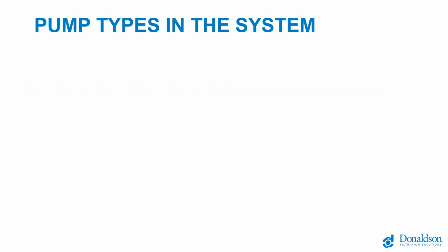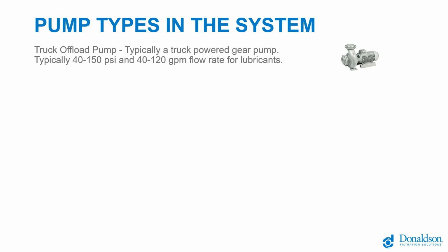So first off, the pumps in the system may be some sort of positive displacement pump coming off of the truck. It's probably not going to be driven by an electric motor there, but there may be a transfer pump on site. But that's going to be a positive displacement pump that probably has a relief valve in it to prevent very high pressure. Even though that pump can push it, the pump will just begin to slip and offload flow rate will drop. But the truck either is equipped with that, or there's a full-time stationary pump there for offloading that fluid into your storage tank.